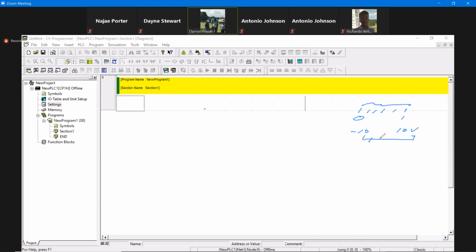you can either choose to have 6,000 spaces, or as is here, you can choose to have a greater resolution. So the spacing, the voltage, the machine can detect greater, well, I want to say number of decimal places, but the thing is more finely divided and the machine can detect a smaller change in the voltage. So you'd have to decide whether you want 6,000 or 12,000. What is the resolution that you are using, depending on the application that you have.